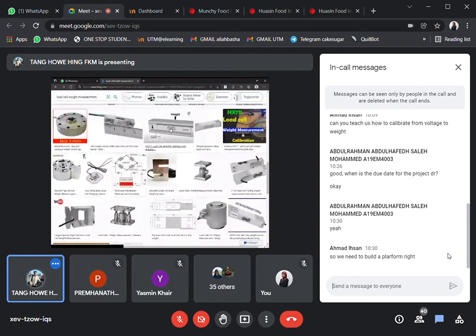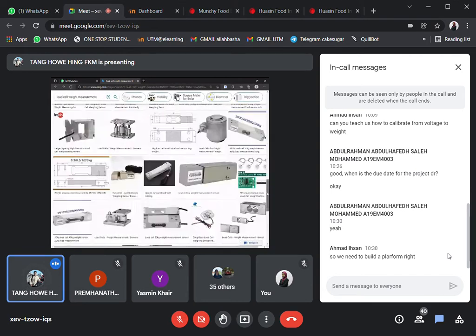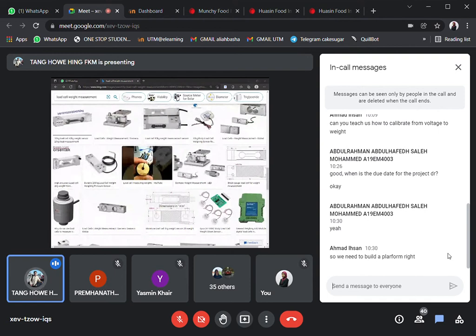But basically, your load cell looks something like this, where you have a kind of hole over here. This expects you to load it through the beam type. Okay, it's a bending type of load cell. So make sure your design is reasonable. Don't make it into the form of a shear type. Okay, I'm not sure whether you understand what I'm mentioning, or what I mean over here. Did you get that? You clear?